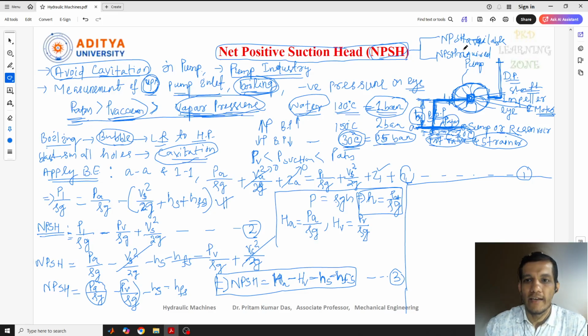So two things are there. The NPSH available we need to find out. And the NPSH required will be given by the pump manufacturer. When you purchase a pump, on the box itself, how much NPSH is required will be mentioned.